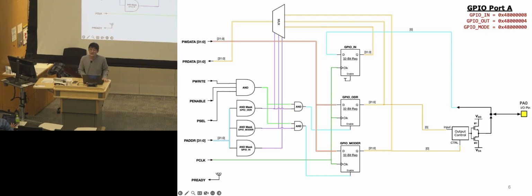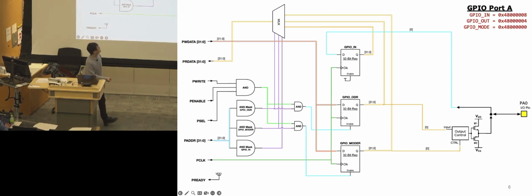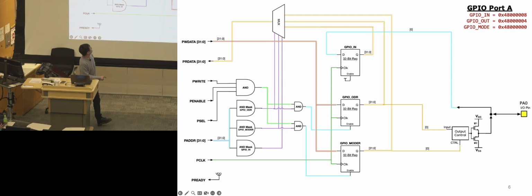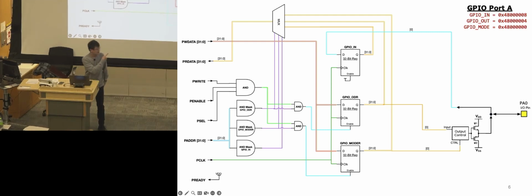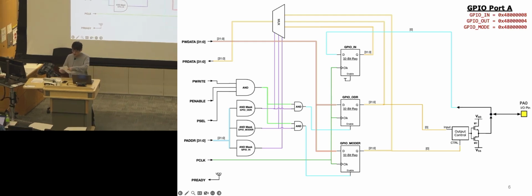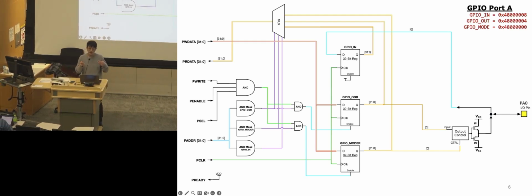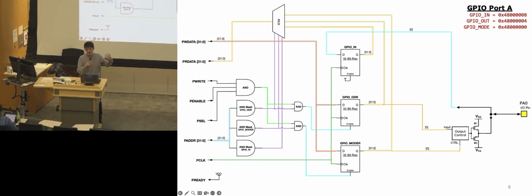You may have already explained this, but can you explain the 0-bit that's coming from ODR and mode to the input? Oh, yes. For this example specifically, it's because the question, sorry, it doesn't have it all printed out, but the question basically asks you to control the zero index of the output, mapping the zero index of the output to that output GPIO. So that's why we put a 0 there, because that's specified by the question. But you could have the entire data onto one pin.